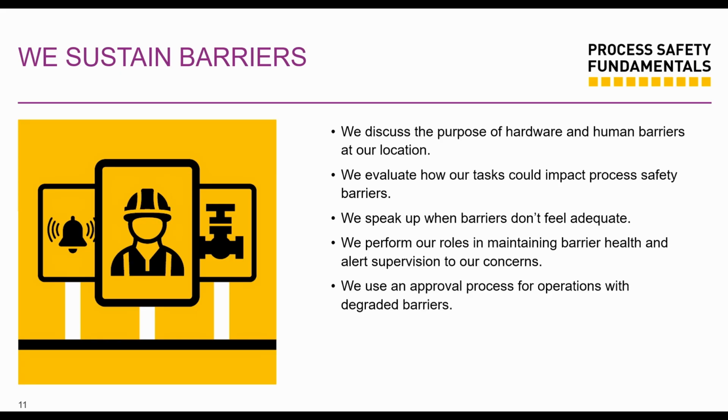Now, a couple of examples. A pressure sensor, a pressure indicator, is faulty, and you don't fix it. You just want to bypass it. But that sensor is supposed to trip a compressor or a pump on high pressure. Because it's faulty, you bypass it, and why not just fix it? Because here you bypass it, the pressure goes above the operating limits, and it doesn't trip what it's supposed to trip, and you have a surge. This incident could have been avoided by replacing that sensor.